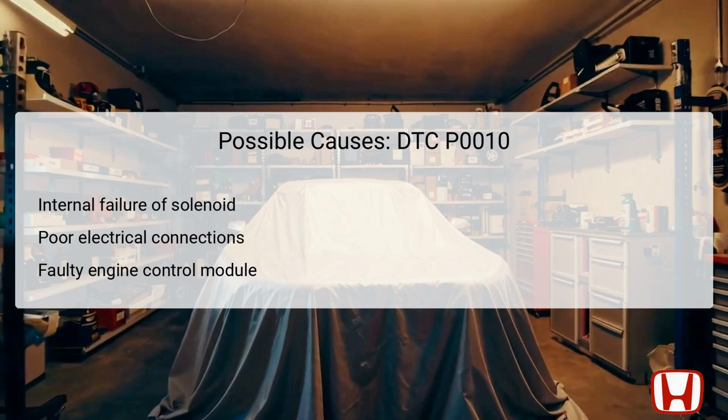Additionally, issues with the PCM itself can also lead to this DTC being indicated, as the PCM is responsible for interpreting data from various sensors and controlling engine performance. Finally, external factors such as oil quality can influence solenoid performance. Recognizing these potential causes is critical for efficient troubleshooting and rectifying the issues related to this DTC.